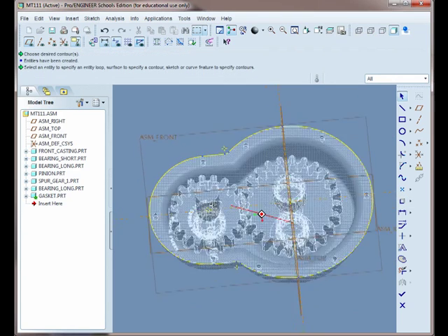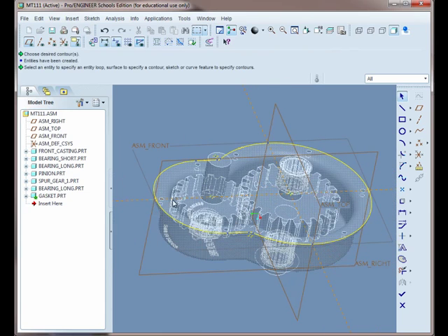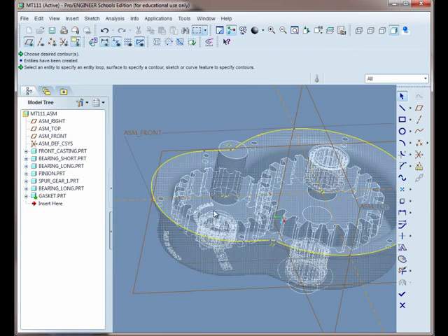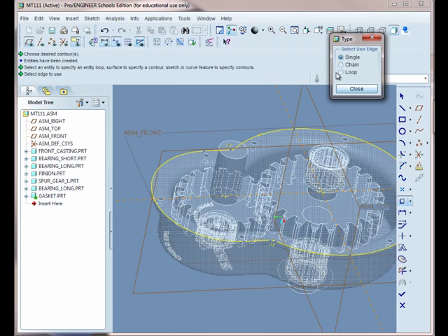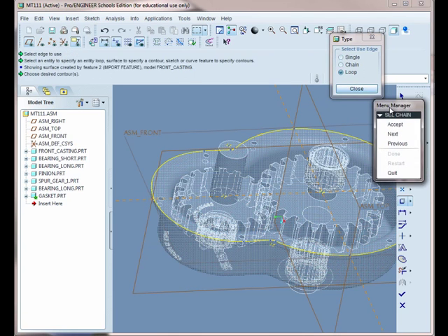Okay, now we stole that sketch geometry. This is why that's a benefit. You don't have to draw in all the dimensions. It's supposed to be the same size anyway, so it doesn't matter. Now, actually, I probably should have kept that up because we're going to grab the inside surface too. So if we go to Use again, we go to Loop and select that surface. And again, under Select Chain, just keep hitting Next till you get the inside.